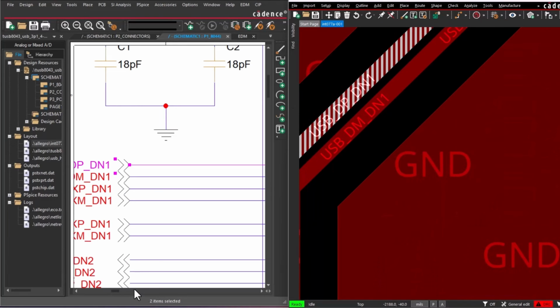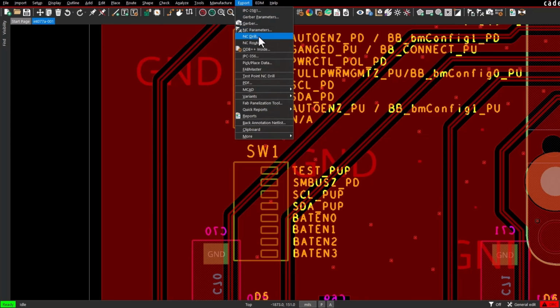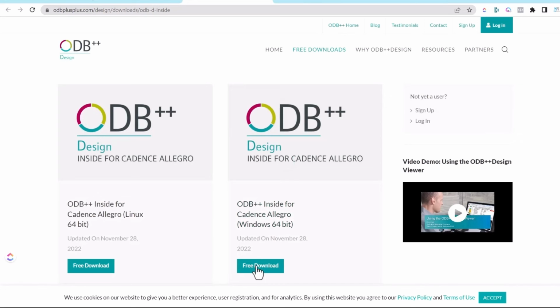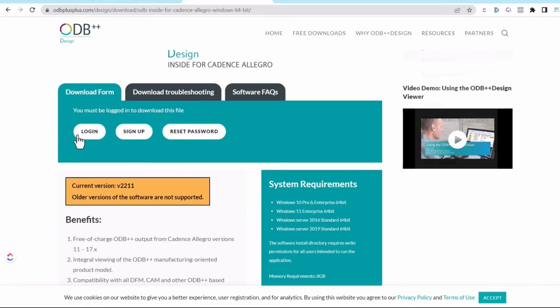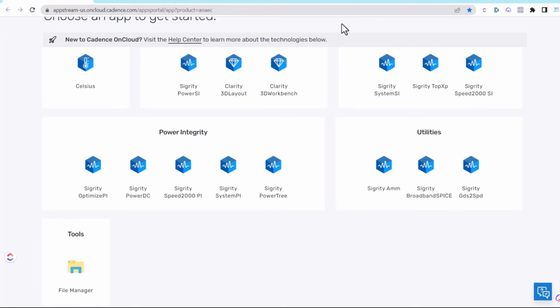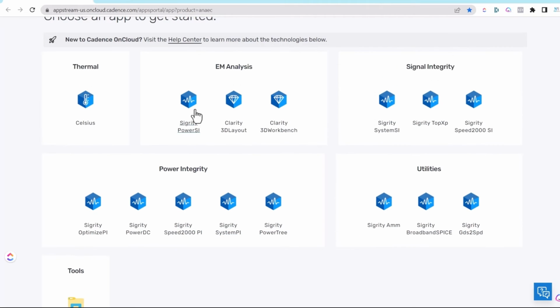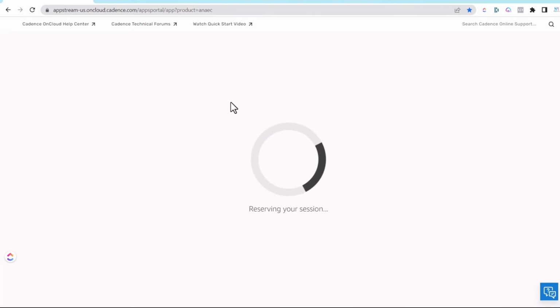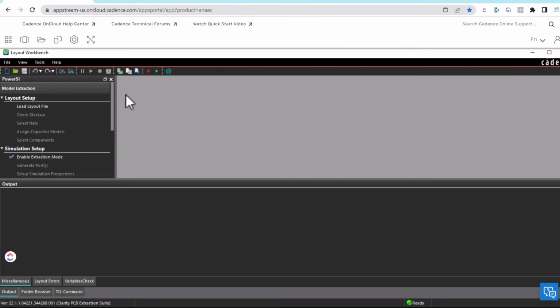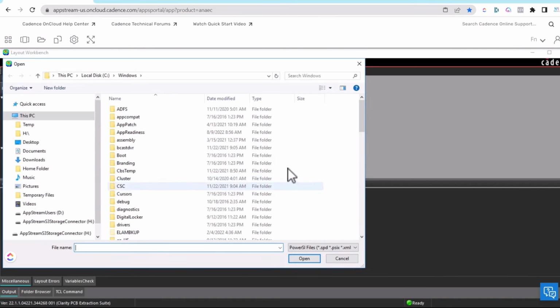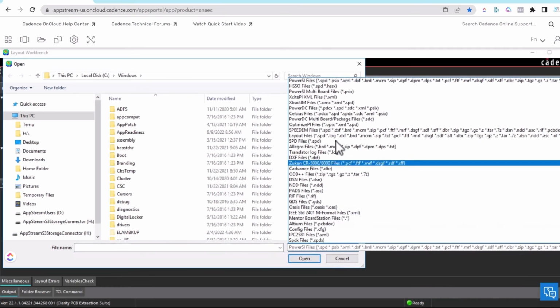Okay, after you're done routing, you're going to need to start simulating your PCBs if you don't already. Once you're done with your PCB, you want to export the ODB++ files, not just the Gerber files, because they have the intelligent data along with IBIS models to allow some third-party software or engineer to use their software to analyze the signal integrity of your printed circuit board. They would send the information back to you based on the simulations they ran and tell you where there needs to be some cleanup, some trace adjustments, where there are issues with signal reflections and crosstalk and all that.